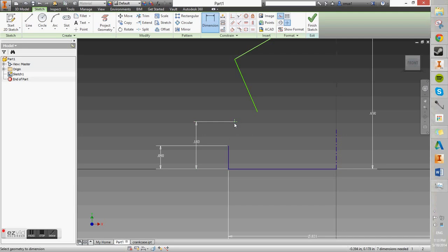So here I'm placing an endpoint where the curve should start. That'll be the same dimensions that we originally had. And then I'm going to use an arc by center point to find the right dimensions. And if you notice, it won't work that way because it still dips below. So I'm going to start from above and then go down until it is perpendicular. There we go. Oh, whoops, that is still a construction line. So I'm going to unselect construction line and do it one last time.